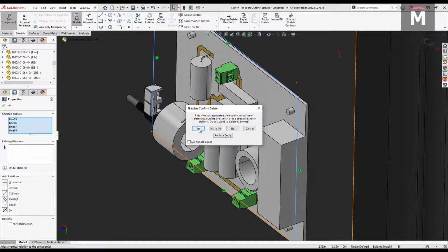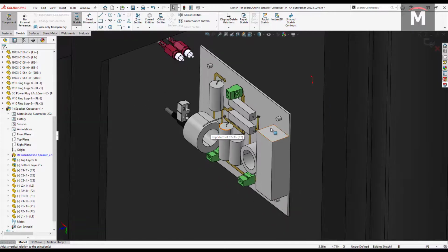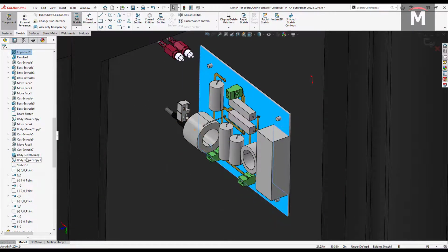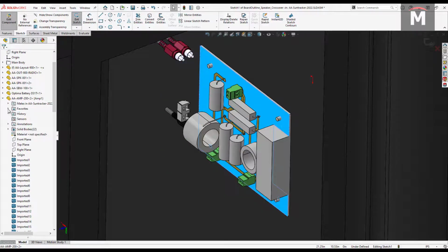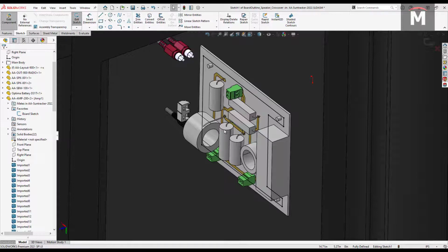Here we have the amp enclosure, and we need to confirm that the board can fit into it. We already have a rough board shape, but this will obviously not work well. I can edit the board shape in context of this top-level assembly and use a sketch shape that's already been approved to fit by our mechanical engineer.